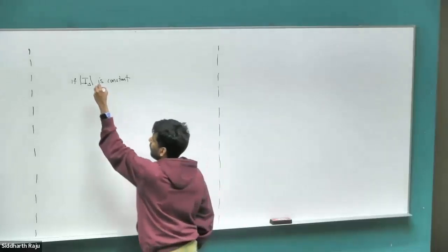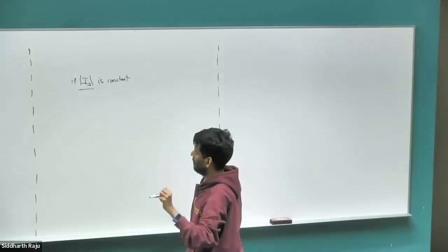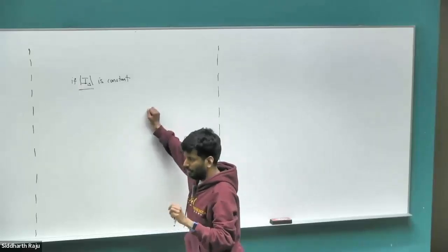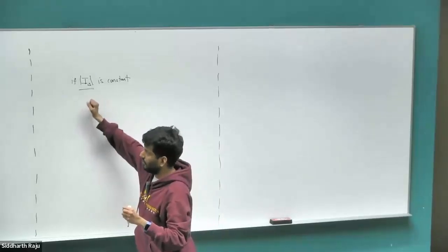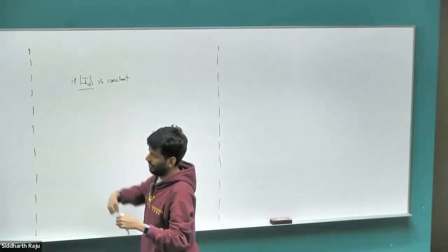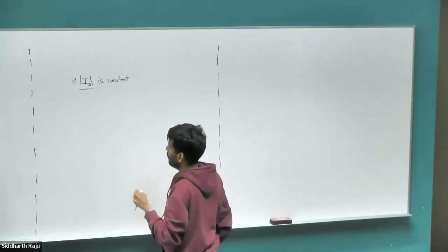So in case of maintaining this current a constant in the basic drives course, we don't worry about how it happens. But the idea is basically we have a similar control mechanism that we have on a DC motor, and then control the current space vector so that the space vector magnitude is a constant, but the phase currents themselves vary in time as a function of the electrical frequency omega e.